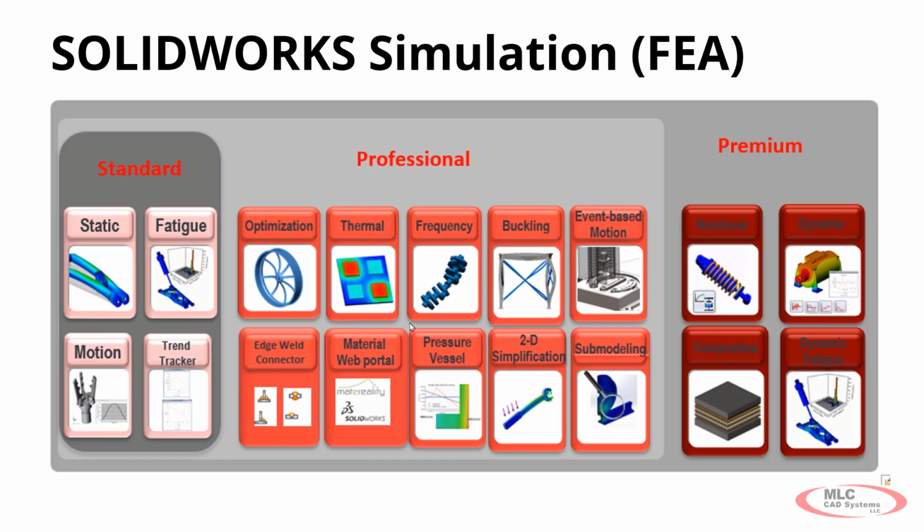Premium is where you go into more of your non-linear studies, which as a base level is, okay, you have higher deformations, you're going past the yield point of your material, so it's permanently deforming. With that, you have dynamic studies, which take in the effects of, if I apply this a little slowly compared to if I hit it, and some things like that.